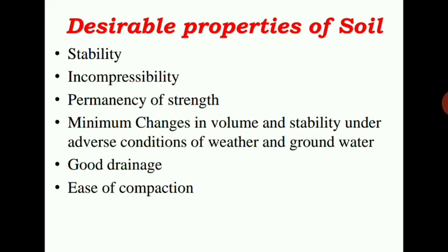Soil compaction occurs when soil particles are pressed together, and the main intention of this compaction is to reduce the pore space between the particles. Heavily compacted soils contain few large pores and less total pore volume, and consequently a greater density.